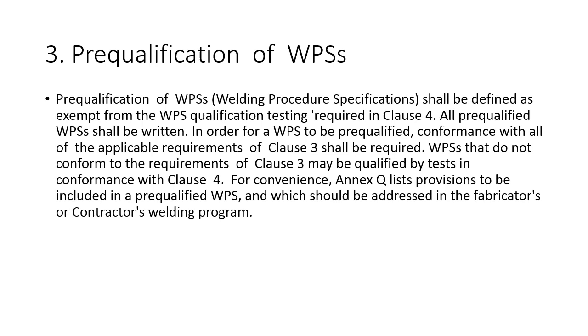WPSs that do not conform to the requirements of Clause 3 may be qualified by tests in conformance with Clause 4. For convenience, Annex Q lists provisions to be included in a pre-qualified WPS and which should be addressed in the fabricator's or contractor's welding program.